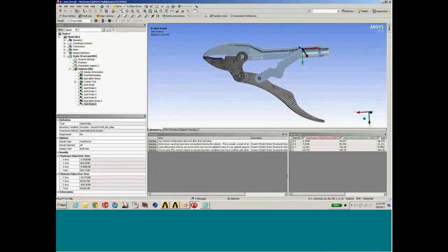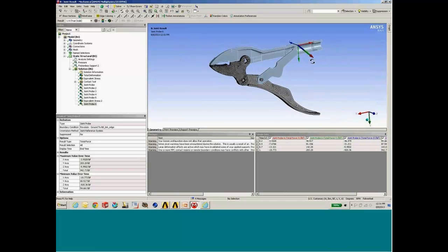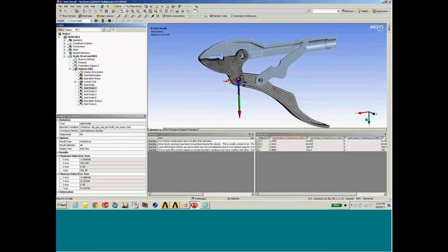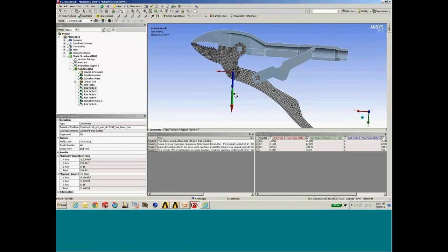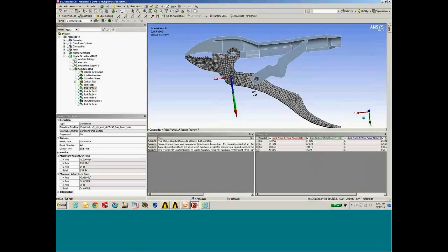Then we simply evaluate the result to get the force distribution. And you can see that's also going to be done, in this case I have a nonlinear analysis with multiple load steps, so you'll see all of the results over the solution history. So it's a quick and easy way to check your results. We'll also do things like it'll give you a net vector of the total load, so basically the SRSS of that load, and the associated vector is shown here.